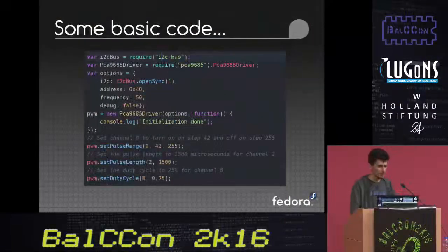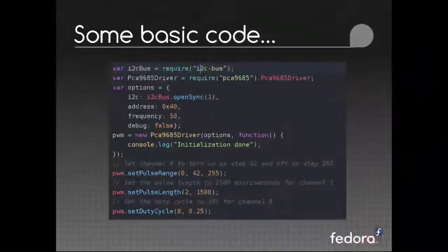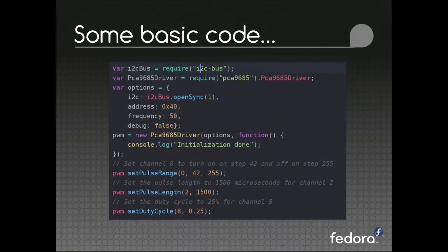And if you want to see an example, it's kind of like this. As you can see, we have to get this code line before we try to use it. So let's say I install it, and I have to require the first two lines. Okay. So these two lines allow me to control I2C protocols, and this is my chip. And then just open my address, my frequency. I have to know it from my datasheet. It is kind of technical, but it's the hardware way.